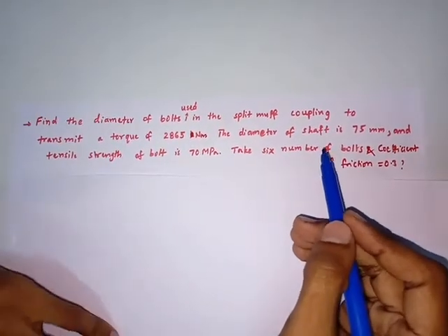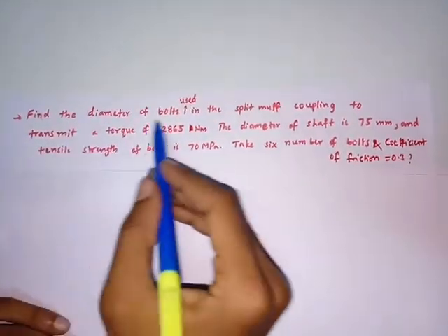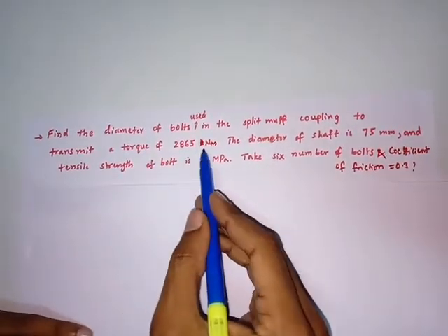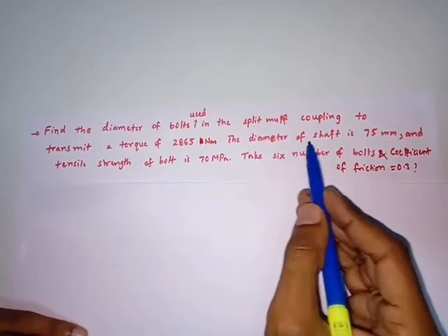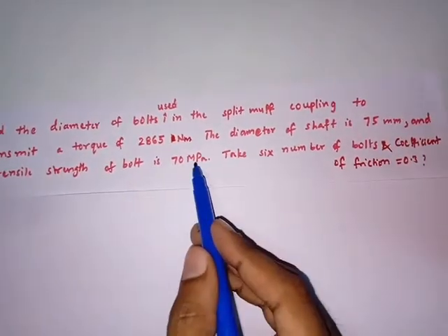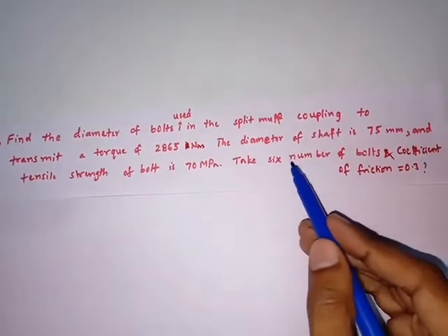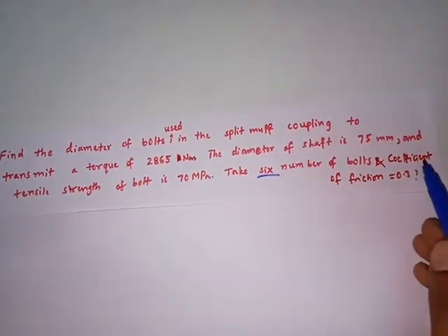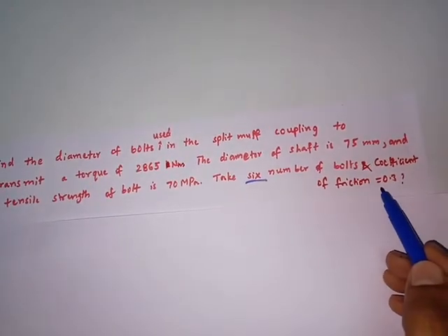muff coupling. So if you see the problem here, find the diameter of the bolts used in split muff coupling to transmit a torque of 2865 Newton meter, and the diameter of the shaft is given as 75 mm, and the tensile strength of the bolt is given as 70 megapascal, and the number of bolts used is given as 6, and the coefficient of friction between the shaft surface and muff surfaces is 0.3.